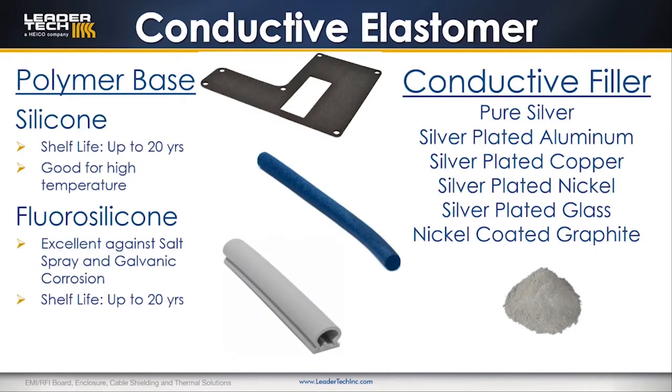LeaderTech's conductive elastomers are made from 2 polymer bases and are mixed with 6 different metallic fillers. Both the silicone and fluorosilicone polymer bases offer shelf lives up to 20 years. Fluorosilicone differs from silicone because it contains trifluoropropyl groups, making it highly versatile for outdoor sealing applications or environments where exposure to sunlight, ozone, chlorination, or aromatic hydrocarbons is common.